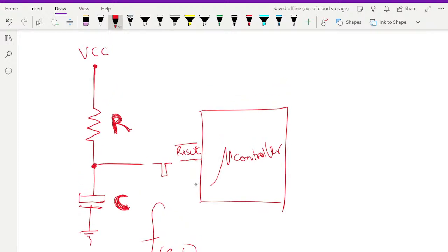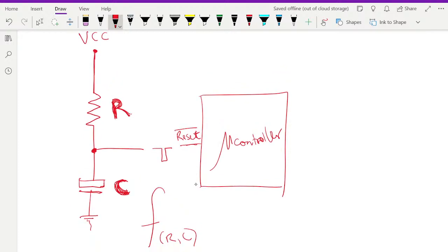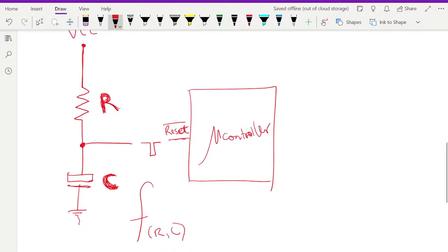So this is one way of doing that. But one disadvantage of this is that the values of the resistor and capacitor are affected by temperature. So it might fail sometimes, it might work sometimes, but for every practical purpose and intent, it should work, right? The period might change a lot, but it should still work.